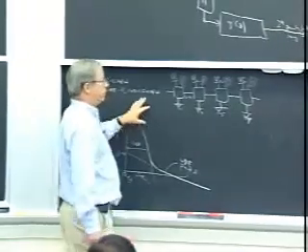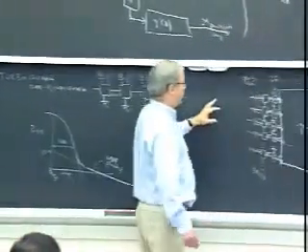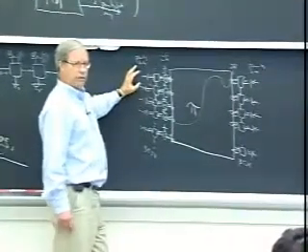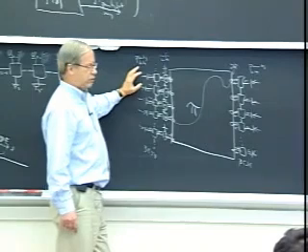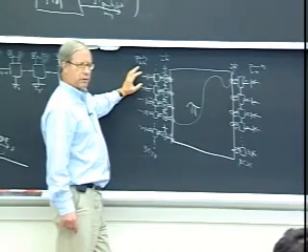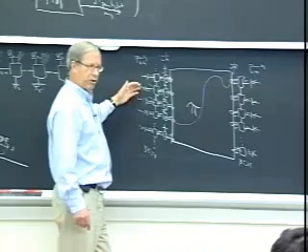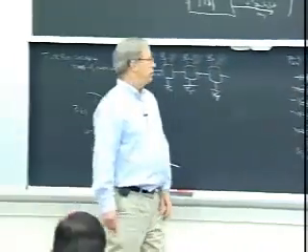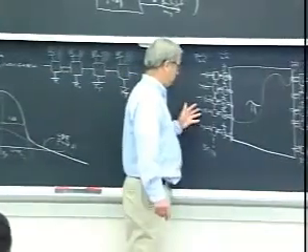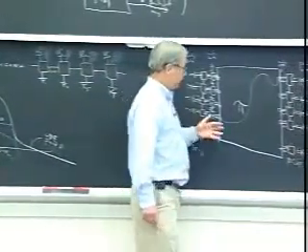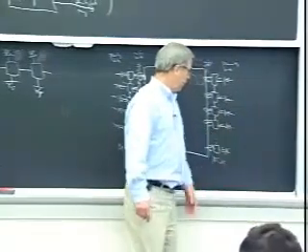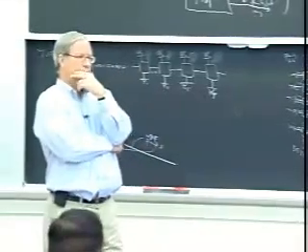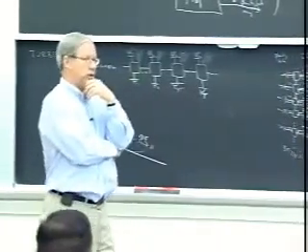One other thing I should mention, very commonly in turbo codes, they don't send all of these bits. They send fewer bits, which in effect raises the rate. But then of course it makes decoding harder because you don't get any received information from the bits that you don't send. There are various philosophies of this, called puncturing, that I'm certainly no expert on. And it's possible that by being very clever about puncturing, you could do something about minimum distance.